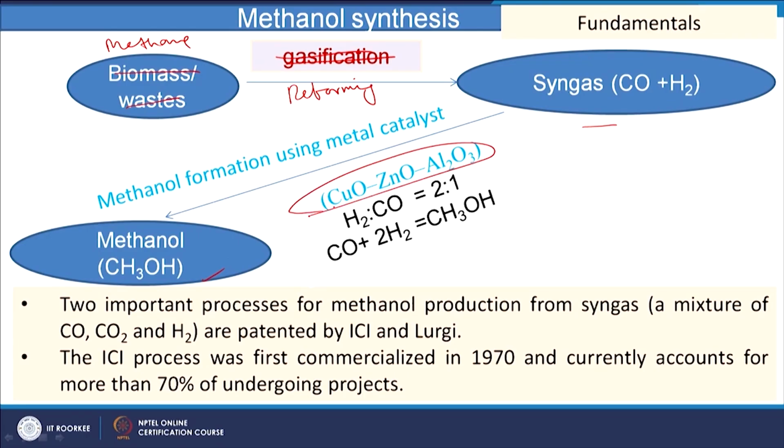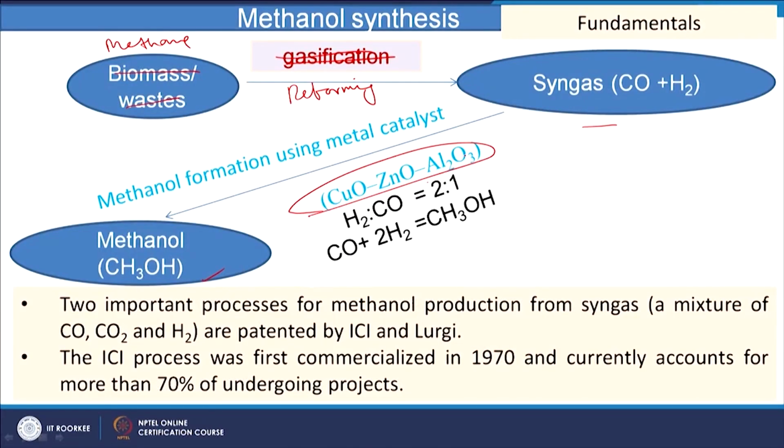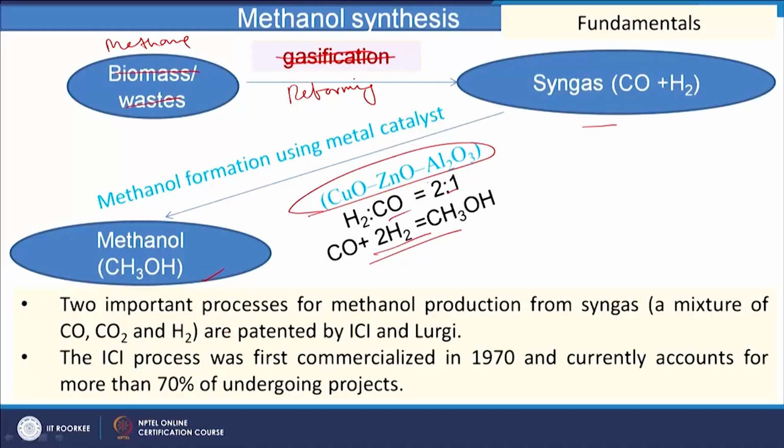So, what is the condition? We need a catalyst, and a copper based catalyst has been used widely, copper, zinc oxide, alumina, and then H2:CO ratio 2:1, and these are the reactions. So, that way we can produce methanol. I have mentioned the overall reactions in a very simple way here, but this is not very simple because it is a gas and solid phase reaction. So, I will discuss more.